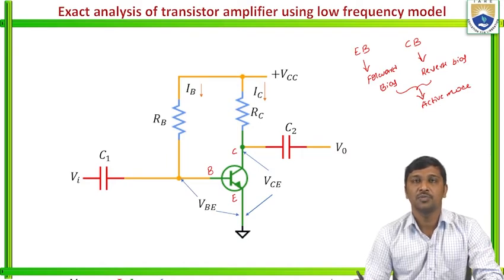To provide faithful amplification, we also observed the Q point analysis or operating point analysis, and always the Q point should be located in the active region, that is, the center of the DC load line. So once the transistor is designed for an amplifier, we need to provide a constant collector current to stabilize the Q point in the active region to provide faithful amplification.